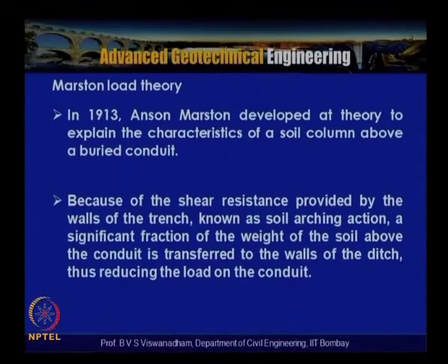This soil arching phenomenon is visible in a number of applications in geotechnical engineering, namely in retaining walls, in tunnels and in buried conduits. From the buried conduits point of view, we will try to see what this soil arching is, and there are two types of arching, active arching and passive arching. We will introduce Marston's load theory and then see how the load transferred onto the pipe can be computed for a given condition.